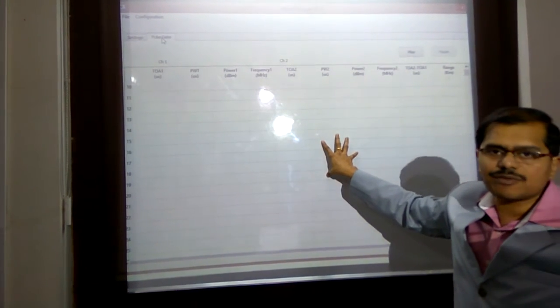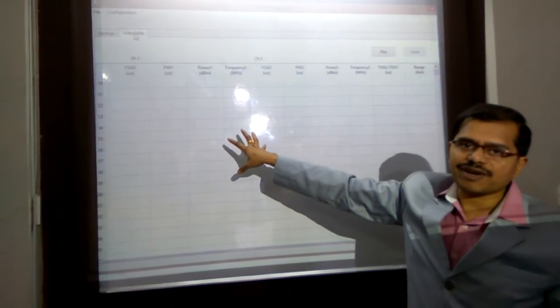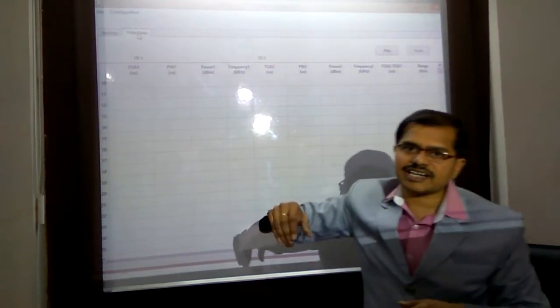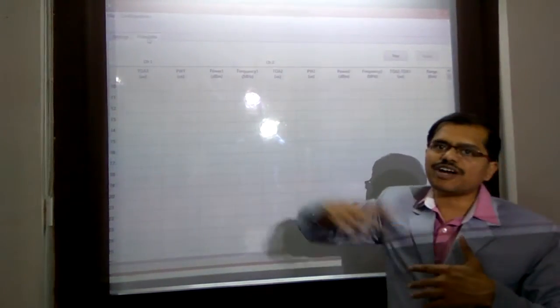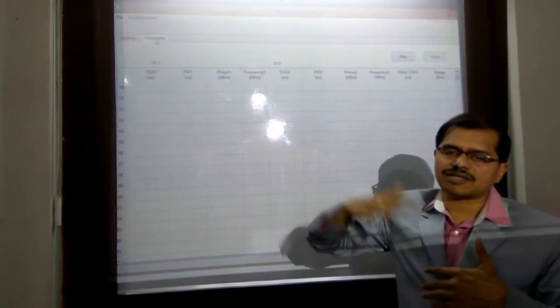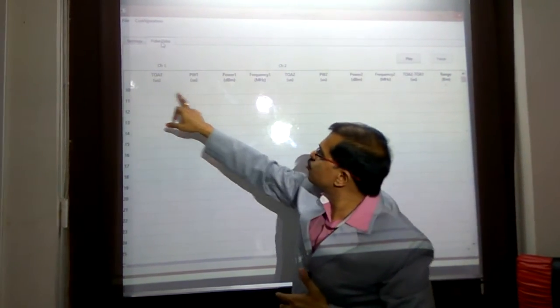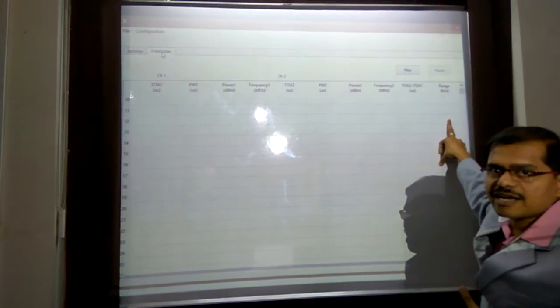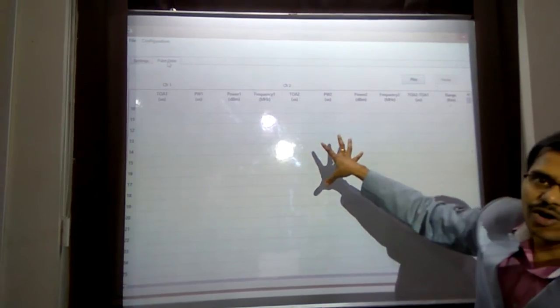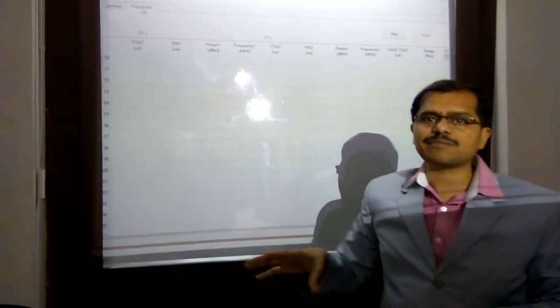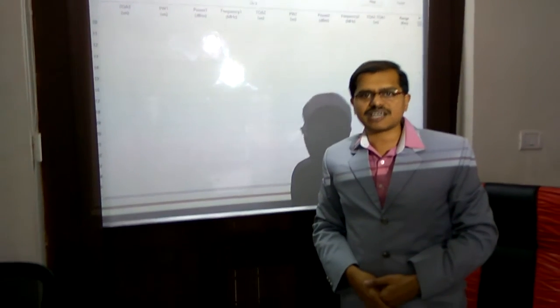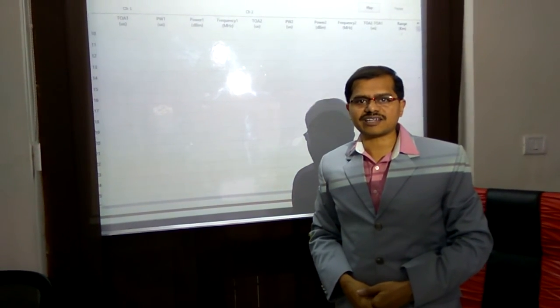Now, when we are demonstrating the radar target simulator, if we set up for a distance, simulating a target at a distance of 150 meters, the to and fro distance between target and the radar is 300 meters, which simulates a delay of 1 microsecond. So when I intercept 2 consecutive pulses of channel 1 and channel 2 and find out the TOA difference, it will come as 1 microsecond. Using this to and fro delay, we compute back the simulated range. So using this product and this setup, we are demonstrating multiple features of the radar target simulator. Please browse other videos which demonstrate detailed features of the radar target simulator. Thank you.